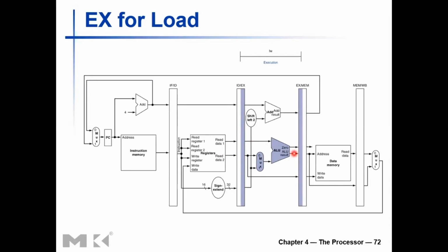At the very beginning of the clock cycle, what you had here in this line was the ALU result corresponding to the previous clock cycle, that is the previous instruction, which is currently in the memory access stage. Now, after a set of delays, we will have the new value available here.